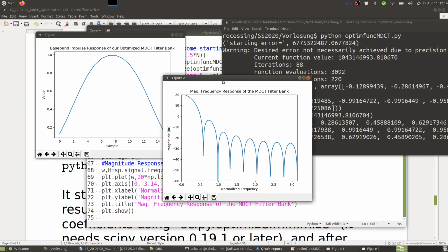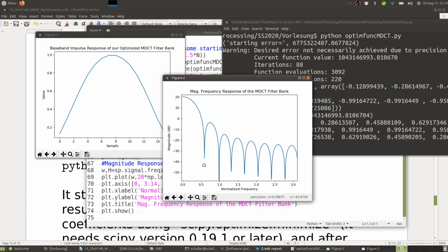And then you look at the resulting frequency response, and you can see here the passband, drag it down a little bit, is about at 20 dB. The absolute number doesn't really matter here, it's relative. And you can see here 20 to maybe -5, so we have about -25 dB attenuation. And then this part has somewhat higher attenuation than in the sine window, and it's more flat. In the sine window it was going down a little bit more, and here it's a little bit more flat,